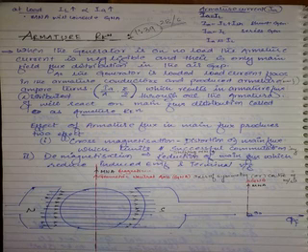Now, the same conductors, when they come under the influence of South Pole, they will have the opposite notation. Now we want the armature flux, how it is. If the current is going away from you, in all these conductors going away from you, so if you hold like this, how are the rest of the fingers telling you? This is the current direction, the fingers are telling you which direction? Clockwise or anti-clockwise? Clockwise, right?